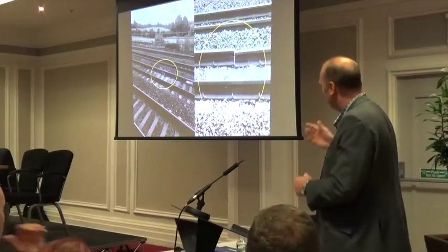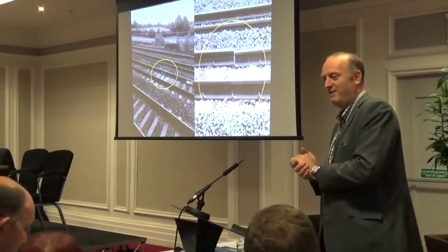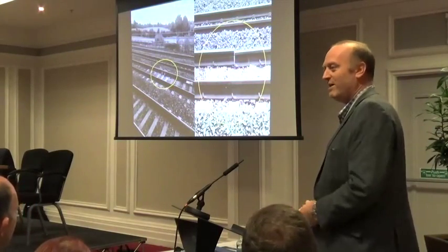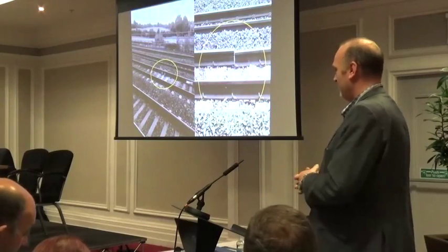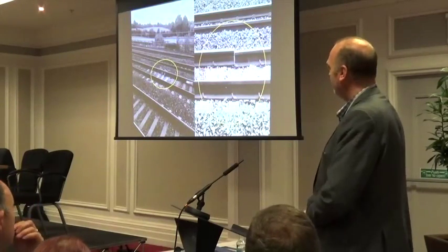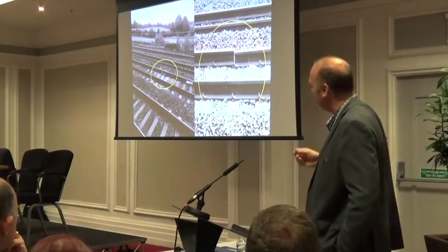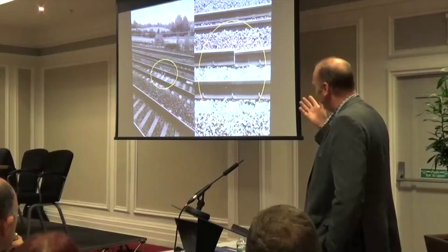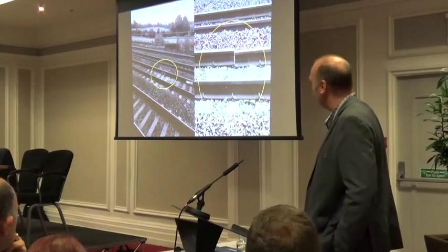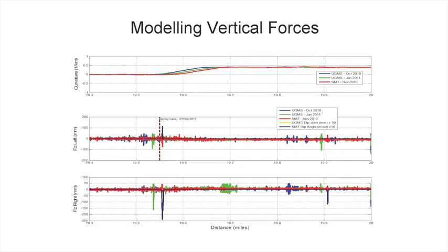And this, I've got to find something to do on Saturday evenings, kept going through recent broken rails, which made me think, what can we do more about it? It's not an obvious fault on a track geometry trace, but clearly something's happening there. There's more energy, the ballast is deteriorating, we've probably got a fair bit of voiding. We can start to model.